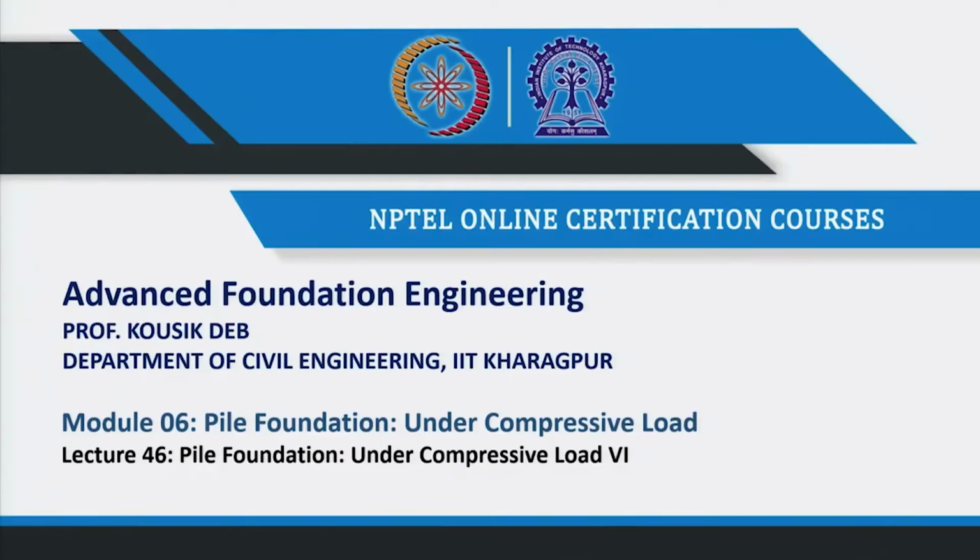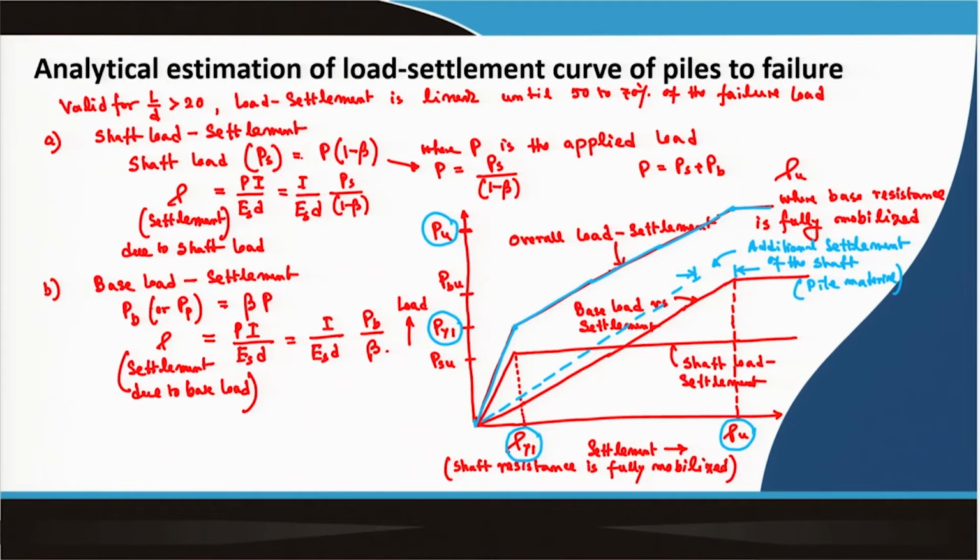So, last class I discussed how we can develop the load settlement curve for a pile analytically based on elastic analysis. This is the procedure that I have discussed, and these are the curves. As I have discussed, first the friction resistance will be mobilized, then the tip resistance will be mobilized, and during the friction resistance mobilization there will also be some amount of tip resistance.